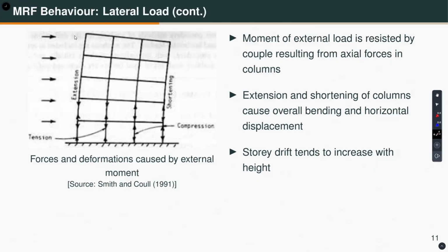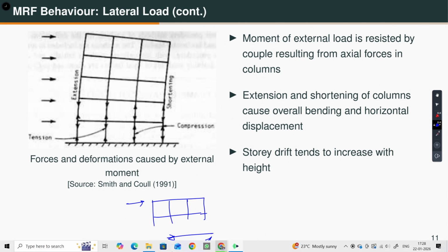But what about if I cut any story, okay, if I draw a free body diagram, let us say something like this, I am cutting any story, I am applying a force here. So, I can always say that if I cut it, I will have a shear force here and it is trying to turn it like so, okay, trying to turn it like this. So, there has to be a bending moment like that. So, this is the overturning moment or the story moment. If you look at the base, it is overturning. At a story level, we call it a story moment.